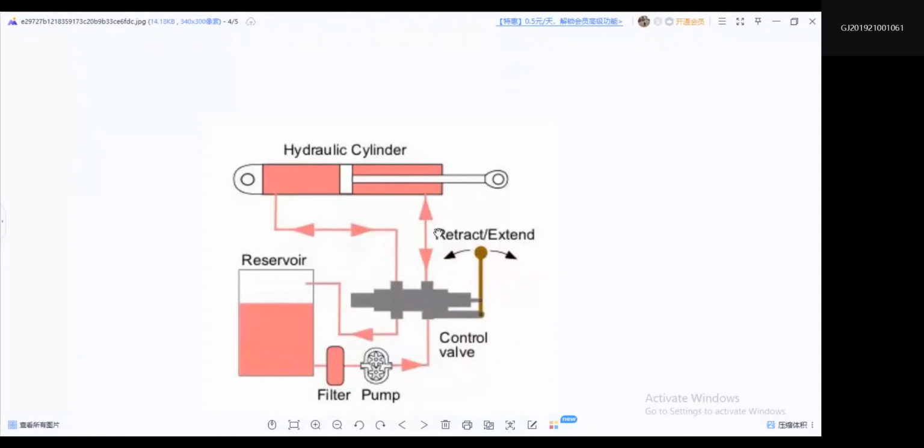How it works: a hydraulic system uses the pump to push hydraulic fluid through the system to create fluid power. The hydraulic fluid passes through the valve and flows to the cylinder, where the hydraulic energy is converted back into mechanical energy. The valve helps to direct the flow of the liquid and relieve pressure when we need it.